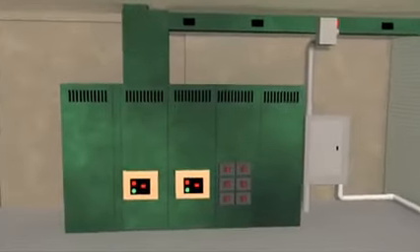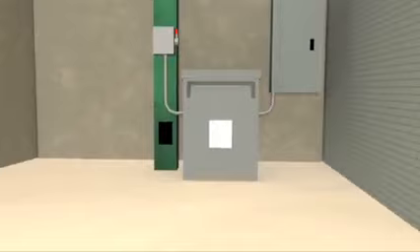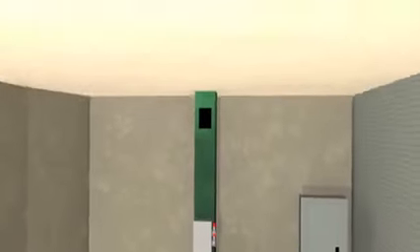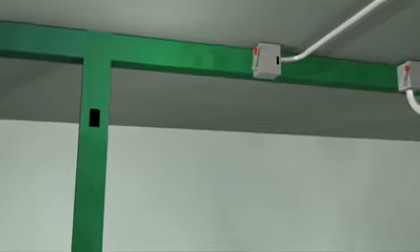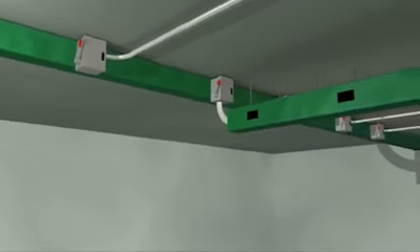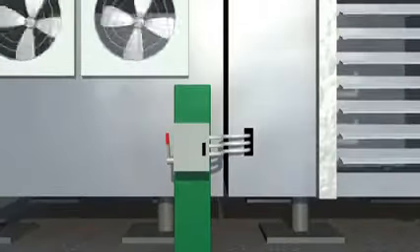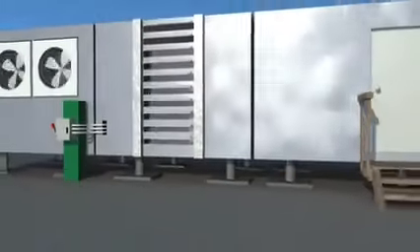In our example facility, you see the bus duct rising vertically to the roof. It passes through an electrical room on each floor. These rooms generally house breaker panels, 1 or more transformers, and or disconnect switches. Power is then distributed throughout the floor. The bus duct reaches the roof to supply power to HVAC systems through a disconnect.